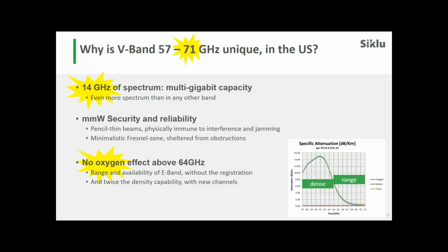Somebody is asking about AES. I thought I talked about AES. Actually, I see another question is related to layer 2 features. Same encryption capabilities on the 614. If you are in an environment where radio encryption is absolutely required, the 614 will do it. There is a license that should be added to activate the features, and you can have all of your traffic encrypted. You need to activate the license on the two radios to have it active in both ways.